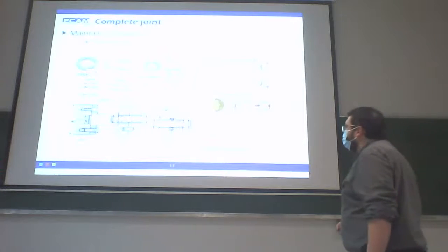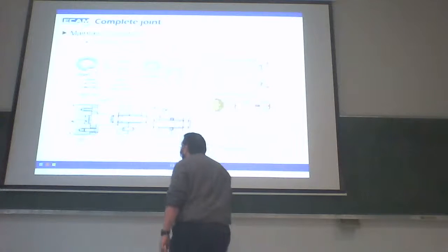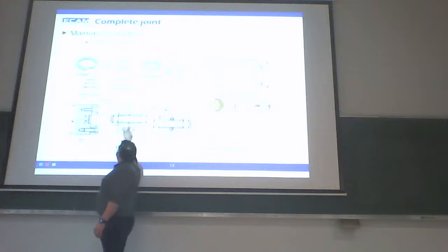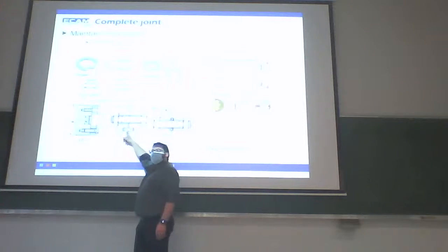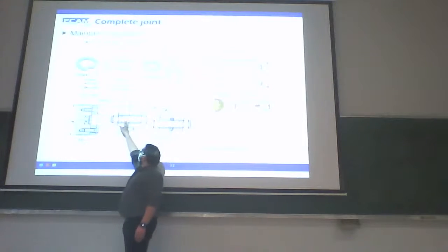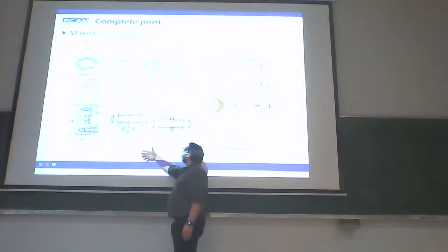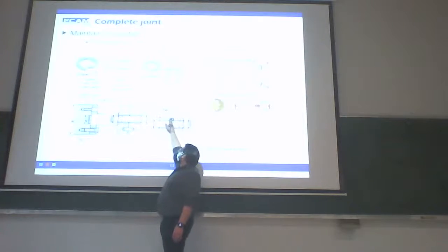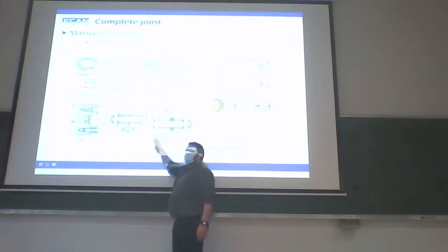Solution 10, 11, 10, 11, and 12. Okay? Here's all the solution with screw. We see that we always use a pin, okay, for relative position to remove all the degree of freedom, and the screws are only here to maintain in position, to fix the position of the part. Okay, so here is the use of the dowel in the middle of the part with the screw in the middle.